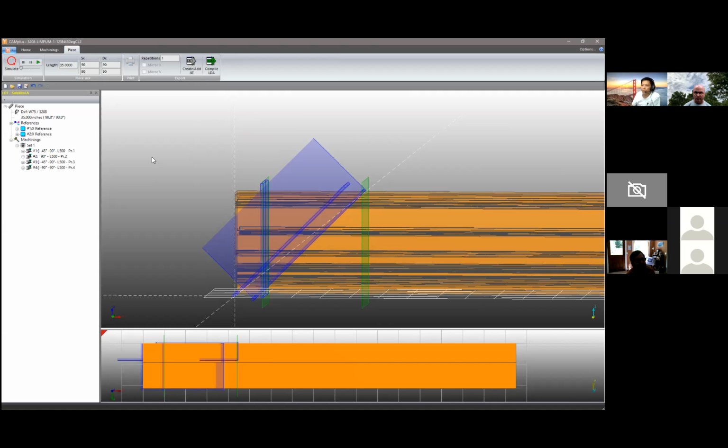Yeah, but actually it's two different tools, but the simulation doesn't show the two different tools, but that's actually how the machine is doing it. Oh, because it's switching to a different diameter tool. Yes, the simulation doesn't show it, but that's how far the tool's going to come up and then just move on to the next one. Okay, thanks. That's why we set the releases as 0.5. We don't want the tools to come out too far, which wastes our time, right? We're wasting machine time on that part.